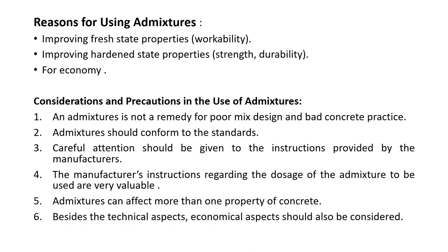Reasons for using admixtures: improving fresh state properties, such as workability of concrete, improving hardened state properties, such as strength and durability of concrete, and for economy.